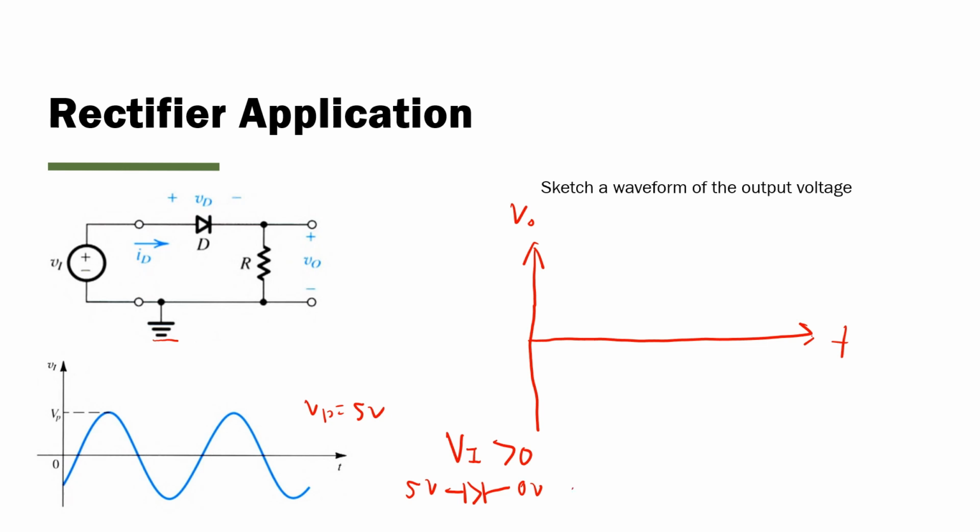So because of that, we're going from high to low. So the diode will be forward biased. And we recall, in the forward bias region, this diode will behave like a short circuit, consuming 0 volts across it. And what that means is the resistor will take the entire voltage from Vi. So that means Vout will equal Vi.